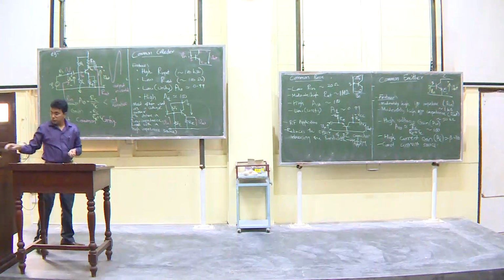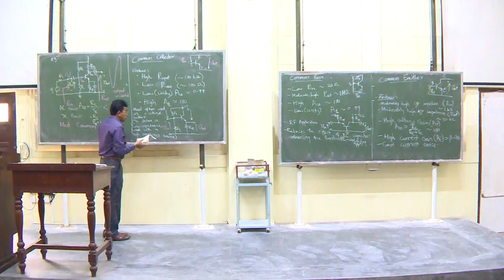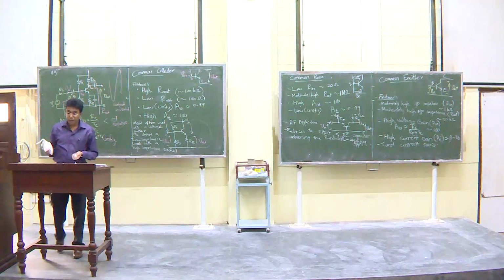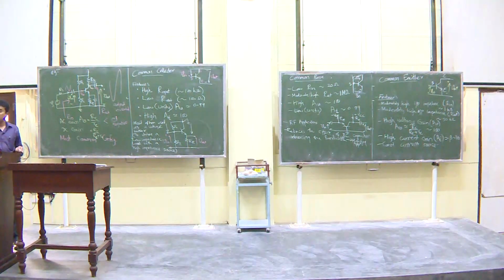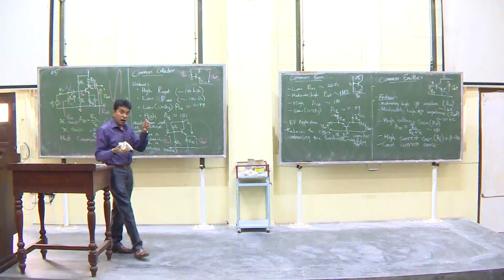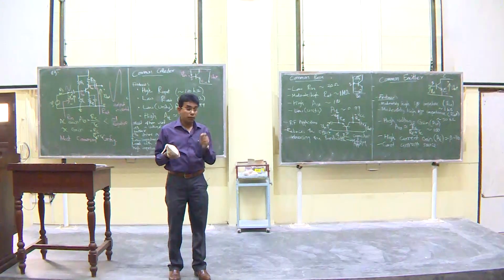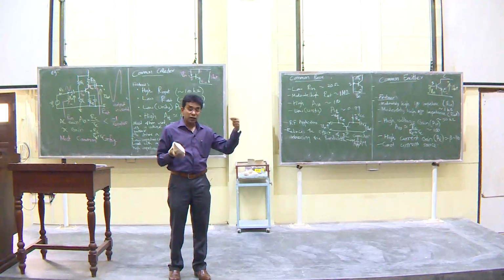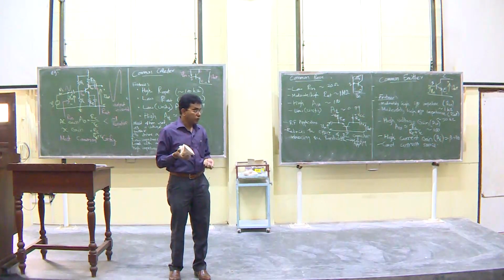Okay, now I think I have about 15 minutes. Let us try to go through the MOSFET amplifier configurations also very quickly, very similar to the BJT configurations, just the names are different. They have very similar characteristics also. The difference though is that because of the MOSFET's gate to channel oxide layer, the current that is drawn is very small, and the input impedance is very large, in the mega ohms range.